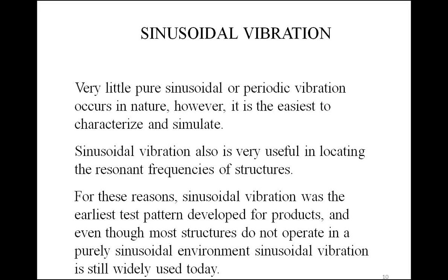So in reality, when we're trying to simulate a condition in the field on a product, very little of our environment is pure sinusoidal. It rapidly became, with aircraft wing flutter and modes of failure that really started all of this testing, that sinusoidal and random are two modes of control that can closely simulate the field.